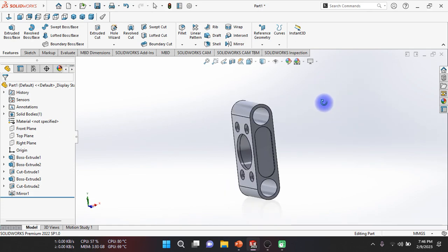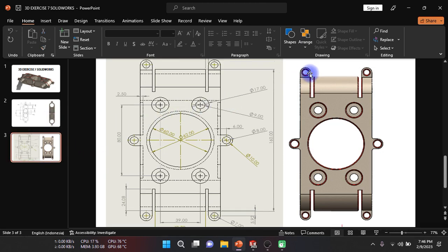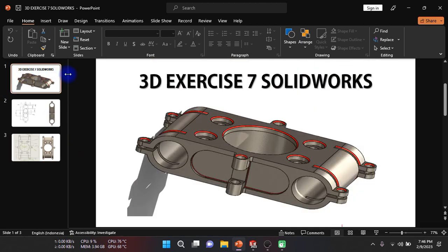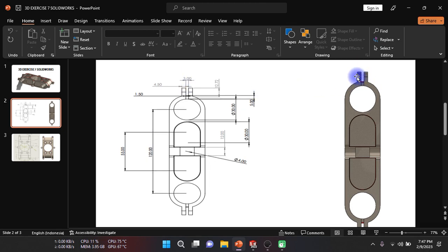After that I want to create this hole. You can see on this part, this hole like this, and if we look at the first part, the total thickness from this line to this line is 4.5mm multiplied by 2, because we have two horns here, and the thickness is 4.5mm, so we multiply by 2 and add 3mm.